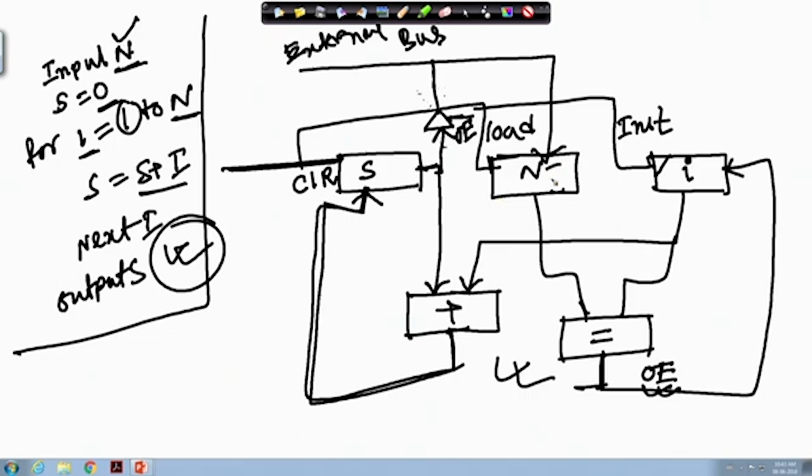So, now if I put n equals 512, in each cycle this circuit will run and it will compute 1 plus 2, then 3, then 4, something like this. As this count value is increasing, initially it is 1, then next cycle it is 2, then 3, then 4, and that is where I am doing the addition.